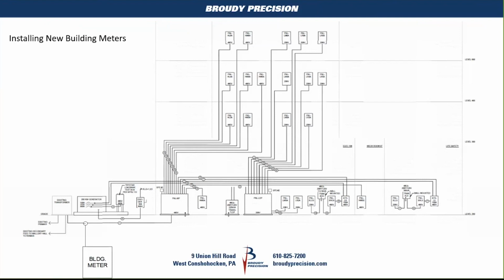It's going to ask us for amperage through our CT rings that we're going to stick around each of the phases, and it's going to ask us for our voltage. And from that, we're going to generate kW and kilowatt hours, of course. So the slide here is for main building installation, but not limited to main buildings.